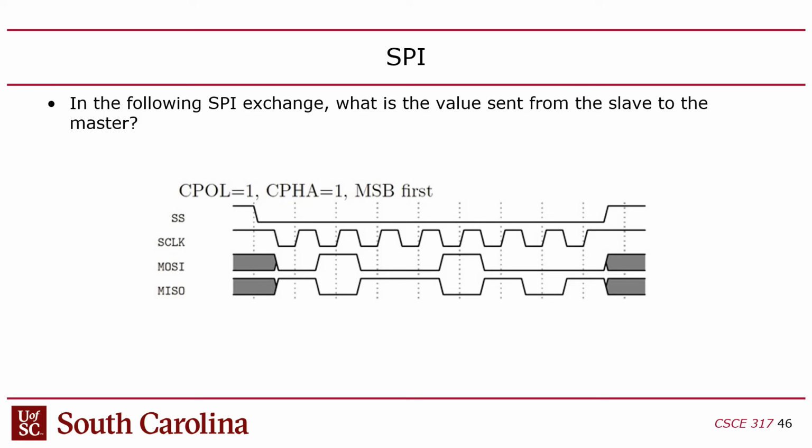Okay, so anyone, where should we start? Clock, right? Okay, which of the clock is either 1 or 0? 1, right. So here, then what does CPHA tell which clock edge we should read? Second one. Okay, so we first just omit it and read on the second one. Just when these dots are. Well, it's just coincidence here, but you can read here.